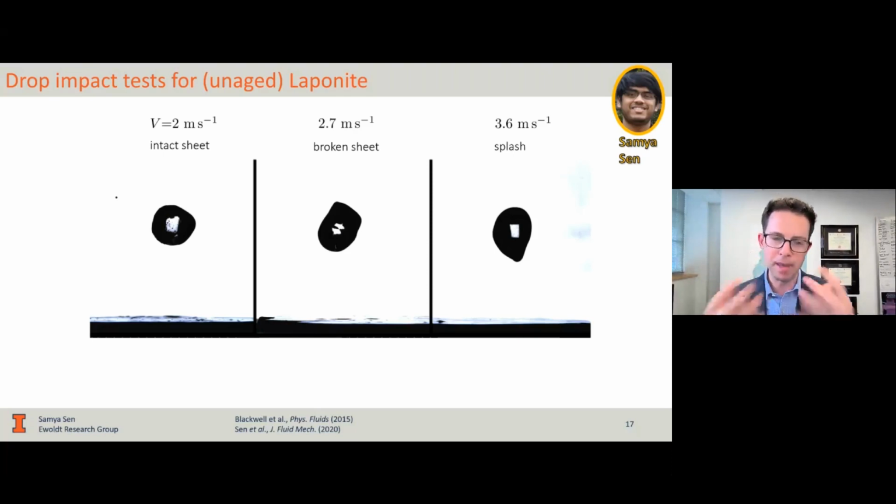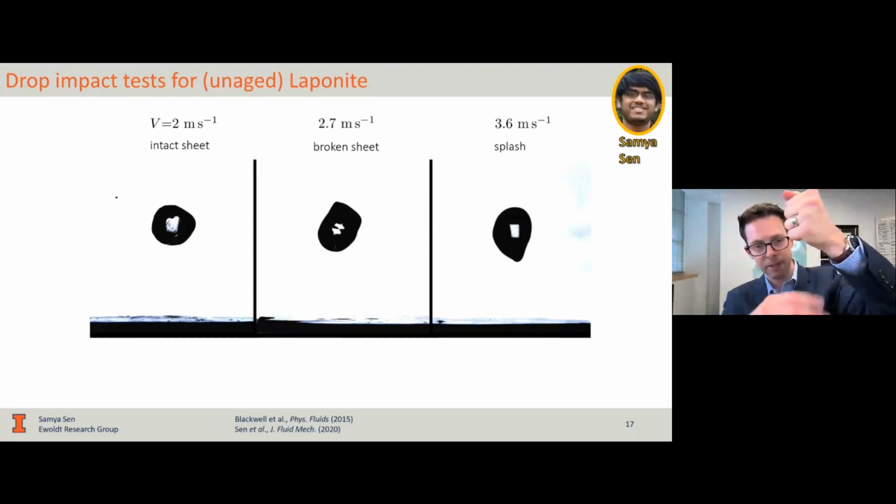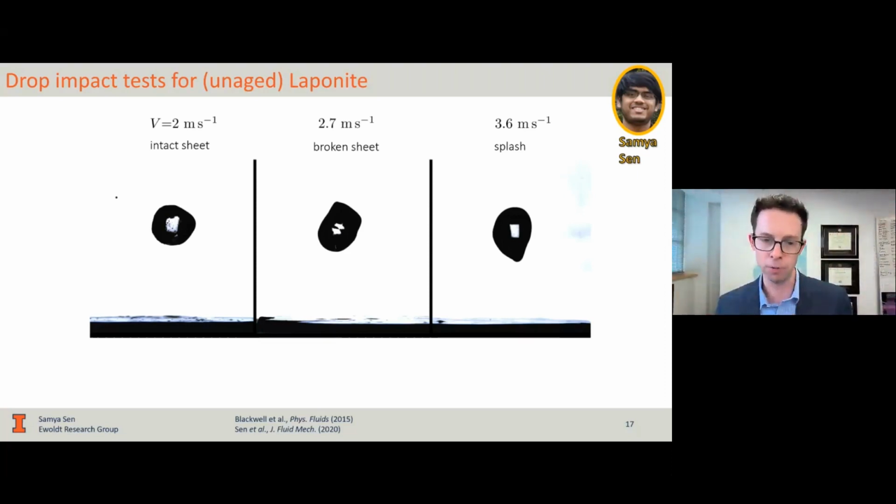And so we've made something that we colloquially call the drop chopper that quickly chops the shape of a drop so that it can fall down in an approximately spherical shape. It requires some super hydrophobic coating on those surfaces so that when we move quickly, it doesn't stick. It's not perfect, but it's pretty good, and it's definitely better than squeezing out a cylinder and chopping off different volumes that then appear as disks, because those edges throw things off more than the inconsistencies we have here.